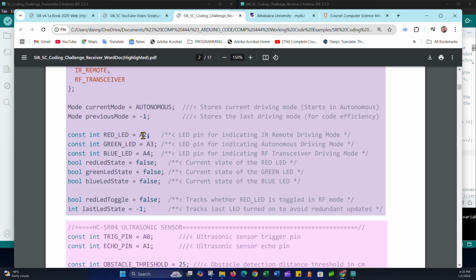And in my case, I needed it because, if I had access to my camera like I normally do, I would show you my circuit and show you that all of my digital pins, with the exception of 0 and 1, which are your receive and transmit pins, are used up because of my NRF24L01 module, my motor control pins, and that sort of thing. So I've used up all of my digital pins.